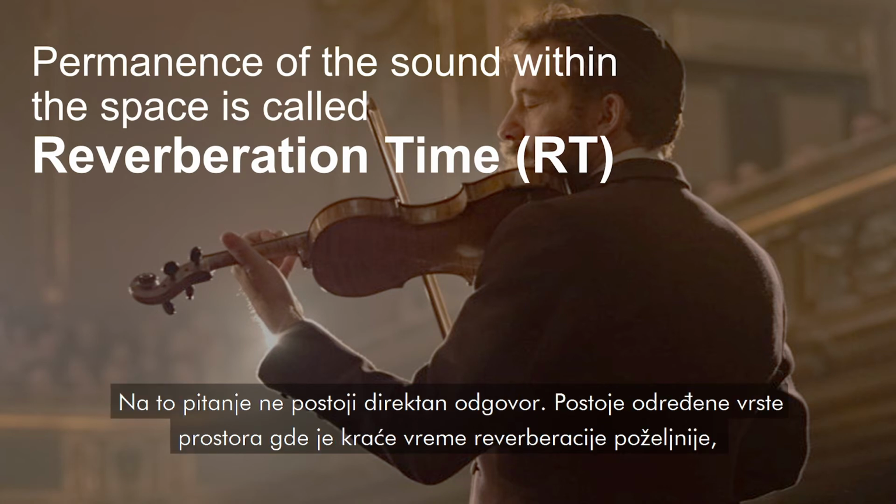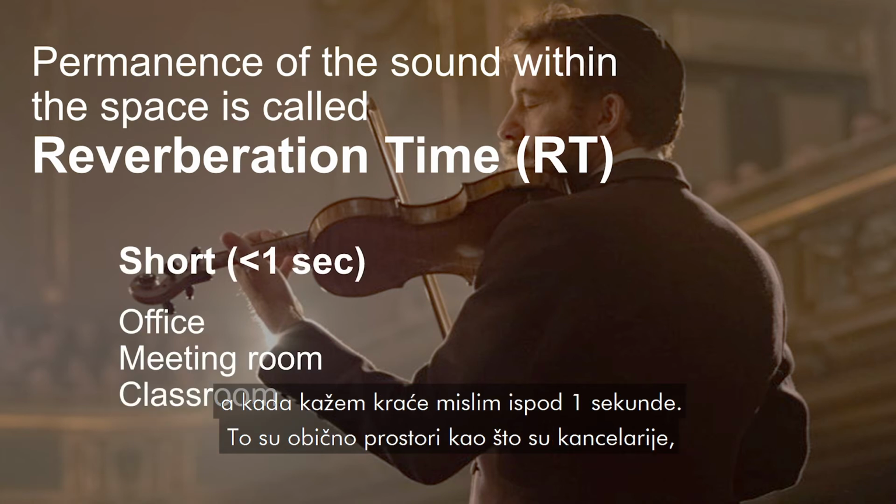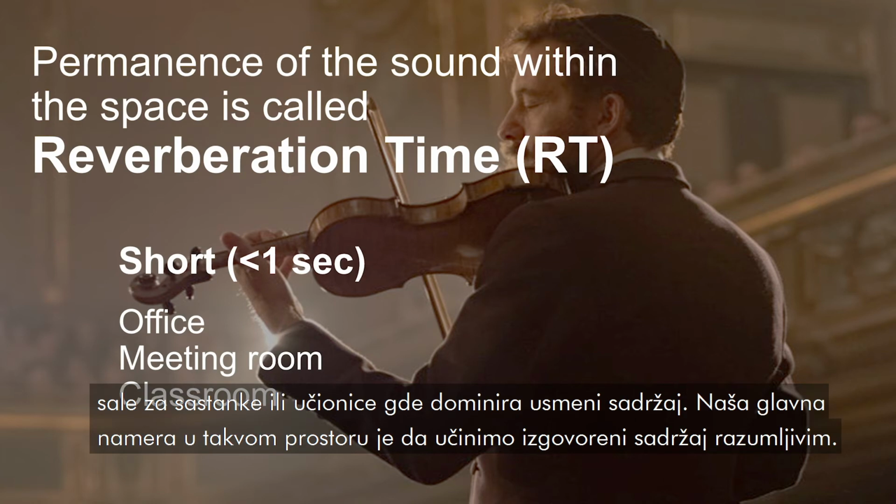Well, I have to disappoint you, there is no straightforward answer to this question. There are certain types of spaces where short reverberation time is preferred. When I say short, I mean reverberation time below 1 second. These are typically spaces such as offices, meeting rooms or classrooms, where it is the spoken content which is predominant. Our main intention in such a space is to make the spoken content understandable.